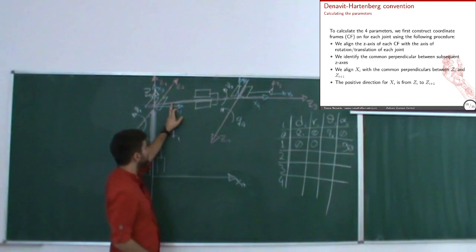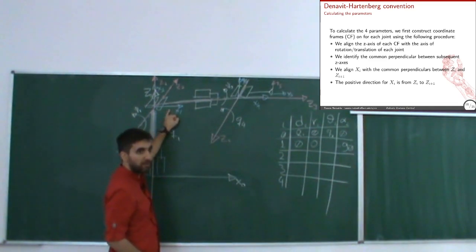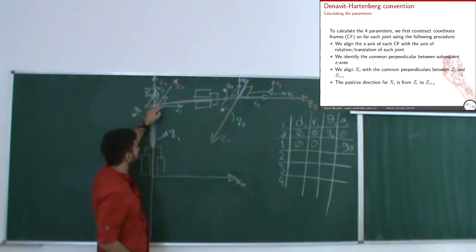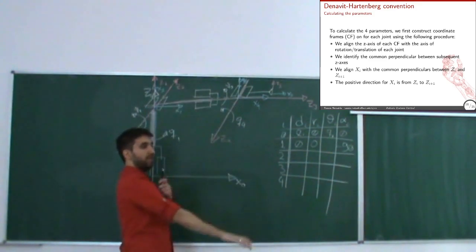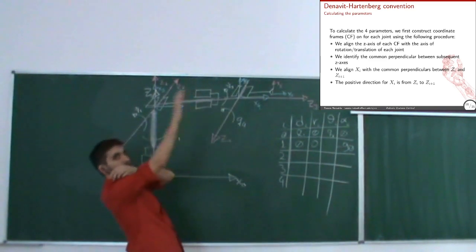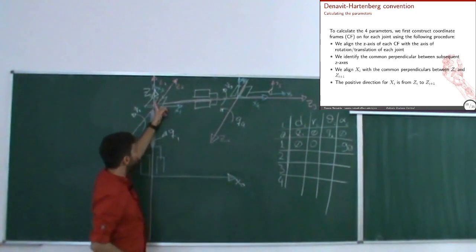But the orientation of Z3, is it changing relative to x1? x1 is perpendicular to Z2 and Z1, okay, and that does not change after Z1, but the orientation of Z3 is changing because I rotate around Z2 by Q2. So I do this thing, and as I do this thing, my x2, which points upwards, is also changing. Therefore, this angle is also variable.